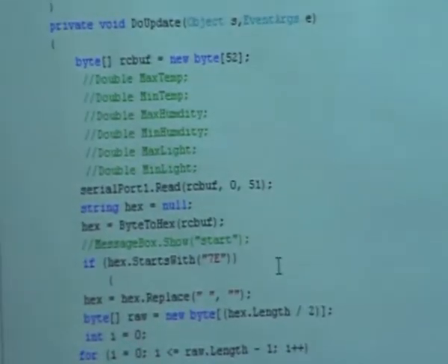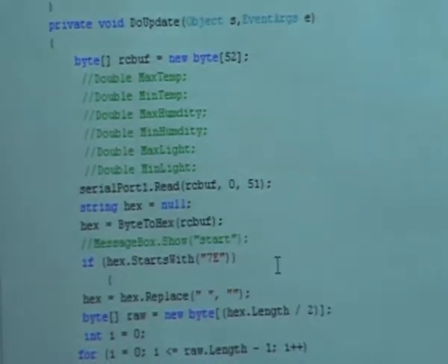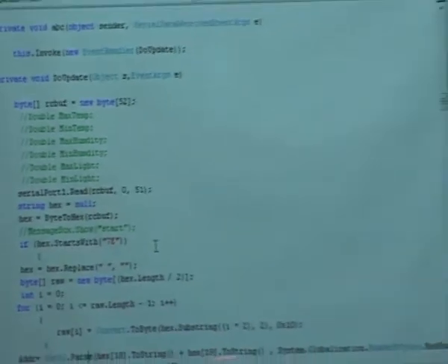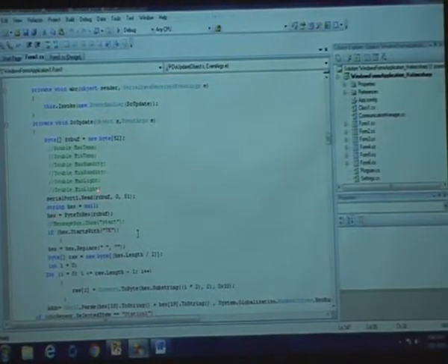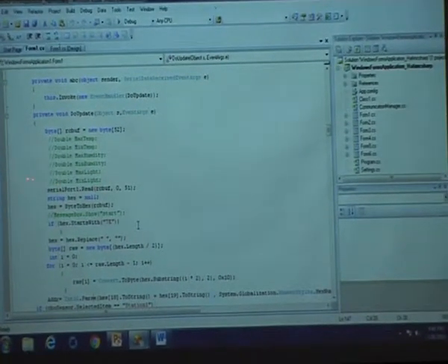So ultimately we are collecting the data from the serial port, and to read the values from it you need to use the read function. Two important things: the serial port should be opened, the opened serial port should read the corresponding values, and after you read the values, they are stored in a temporary array called the received buffer, RC buff.